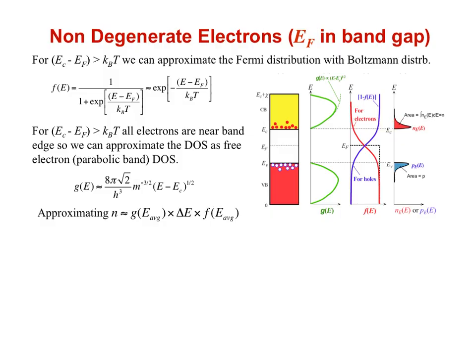The height of the rectangle is given by the energy range that most of the electrons are in, or delta E. The width of the rectangle is approximated by the average density of states of those electrons and their occupation probability F. We approximate that this average energy above the conduction band edge is proportional to the thermal energy, or kT.